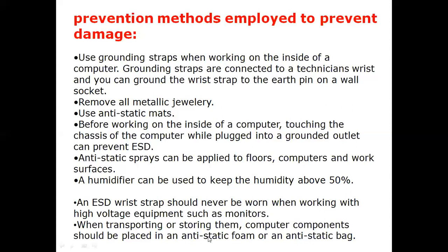When transporting or storing them, computer components should be placed in anti-static foam or in an anti-static bag. Whenever you want to carry your computer component from one place to another by using some transportation media, then you should use an anti-static bag to keep your computer components.